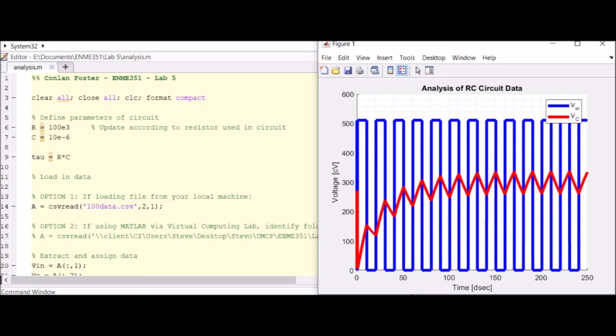For our 100,000 ohm resistor, we see a more atypical plot. Each step of the voltage input causes a decrease in the capacitor voltage, which levels off at around just over 3 volts rather than the 5 volts we would expect from the previous part. Nevertheless, we can still see how the capacitor charges in the same general concave manner.